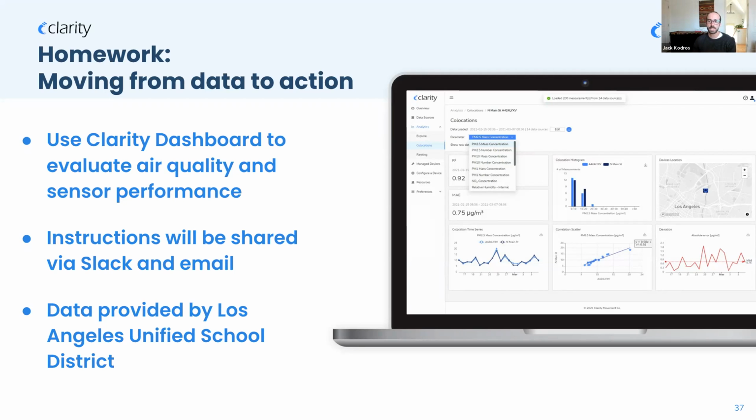That's a really important application, to be able to measure ambient air quality in developing countries, especially places that don't have the infrastructure that the EPA monitoring network has. Often these sensors work quite well in higher concentration ranges. The important part is to simply calibrate them for these higher ranges so that we can properly correct and continue to evaluate them.